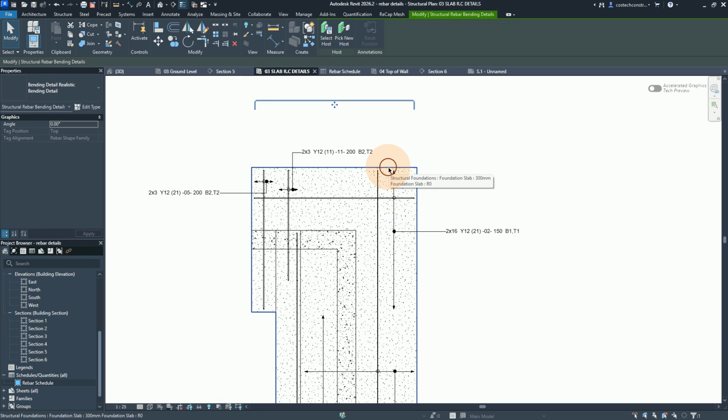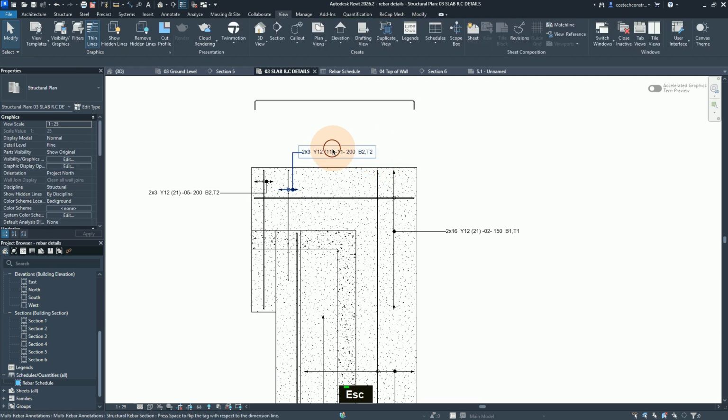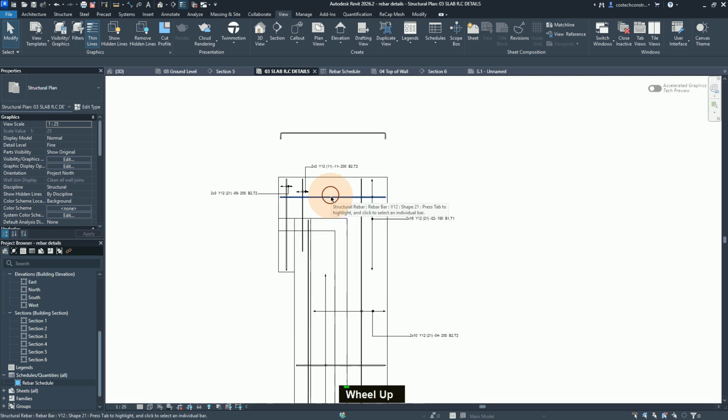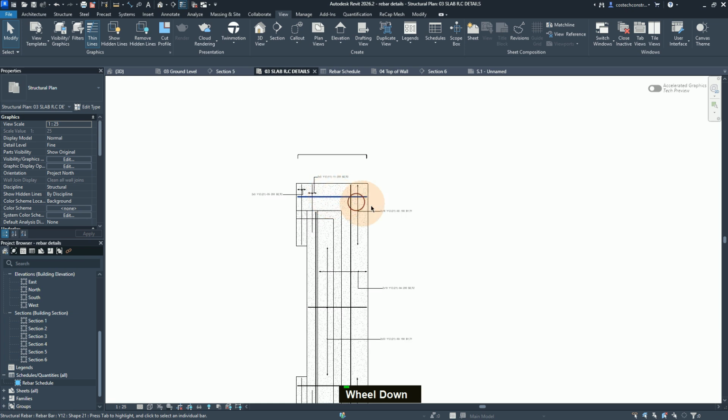Now we have discussed creating the structural tags. Okay, we can proceed to create one section that we can use, and also we can discuss creating the general notes. Now for that, I'm going to open a document that contains my general notes.